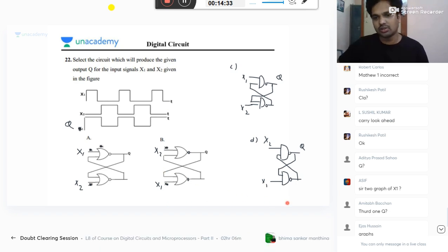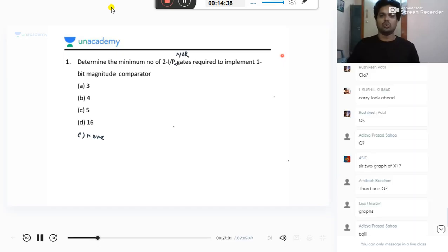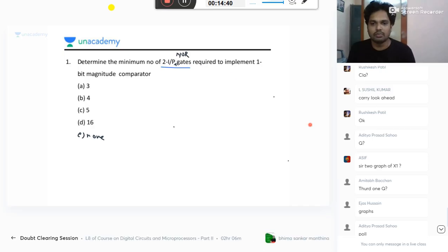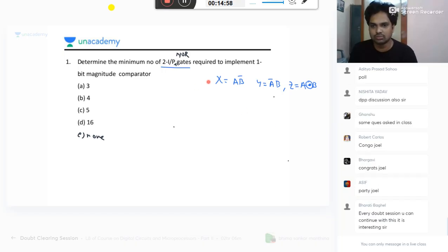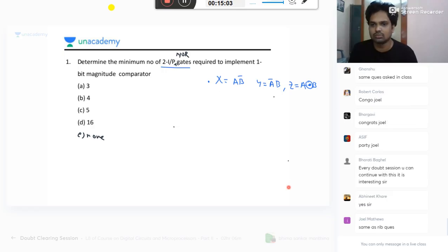Simple rule, Qn 0. Okay, you can also do like this. In a JK flip-flop, one of the inputs is 1, the other input is 0 or 1. In this case, anyway 1. In this case, Qn bar. What is Qn bar, sir? 0 bar is 1. Like this you say, the answer is the same. Or always I love the characteristic equation, because it will give all answers. Everything can be done from this. For conversions, everything it will be helpful. This will help you for any single case.